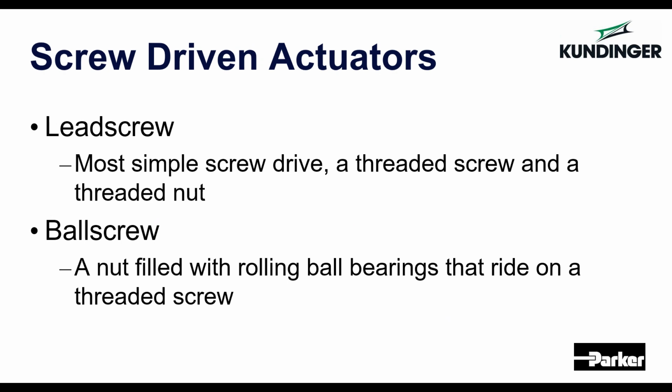Imagine you have a stationary nut, a nut that you are holding and preventing from rotating, and you spin a threaded screw, it's going to move the nut forward. Lead screws are incredibly cost effective, and trapezoidal type profiles can be self-locking. You can also tolerate a good bit of contamination.